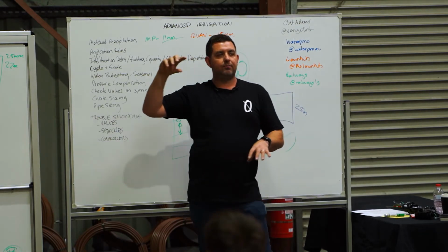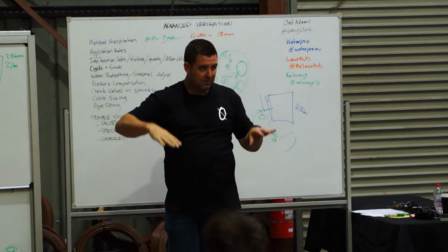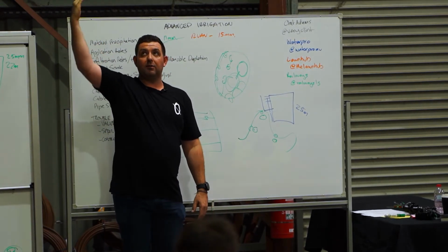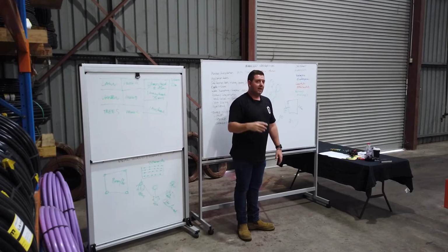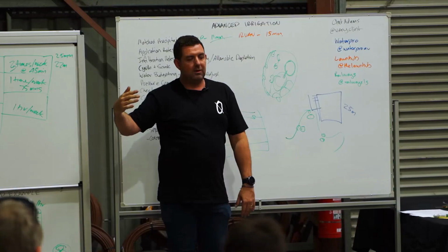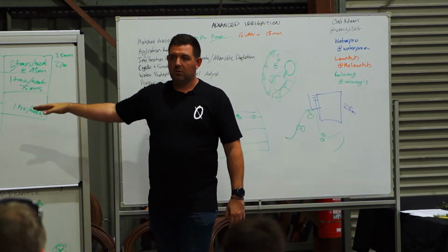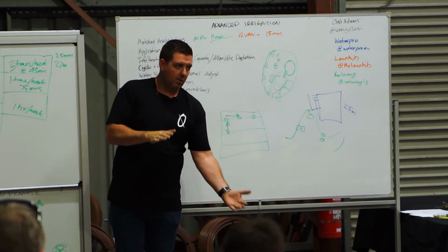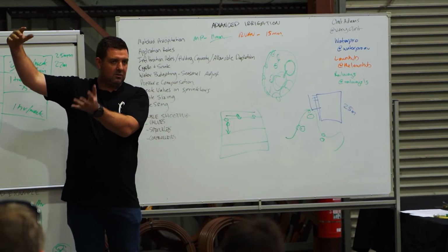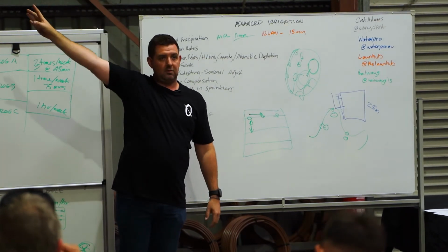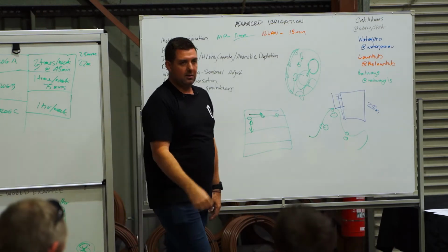It only works to a certain elevation. So once we start getting dramatic elevations, so if we had plants on the top of the pallet racking, 4 meters up, and plants down here, the actual head again comes into play. So we're actually getting different pressures because we're so far apart. When we do that, we would design the drip tube. Say this was a hill, we'd have drip tube running across the hill. The bottom 2 meters would be on their own station and the top 2 meters would be on the next station, so that they're not impacting each other, especially when you turn them off, because every bit of water that's in the top 2 will come out the bottom 1 and then you'll get flooding.